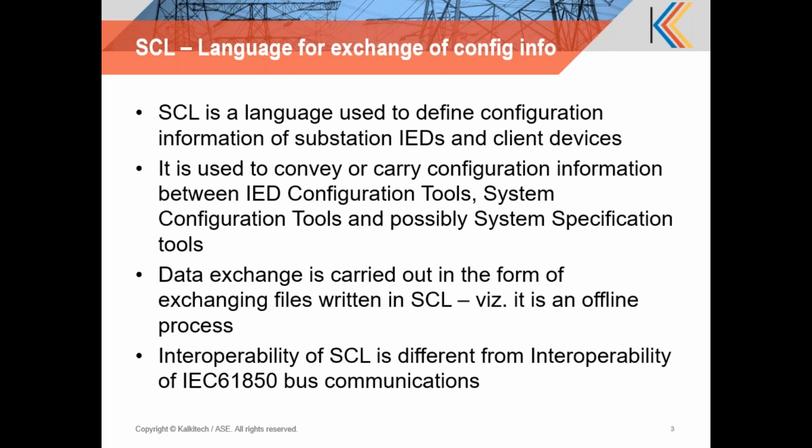As I promised, a quick one slide introduction to what is SCL. Well, SCL is a language. It is used to define configuration information of substation IEDs and client devices. So it is used to convey or carry configuration information between tools. Just like the IEC 61850 protocol is used to convey or carry operational information, control data, or parameters between different IEDs and clients. In the same way, this language is used to carry configuration information, and that is between tools.